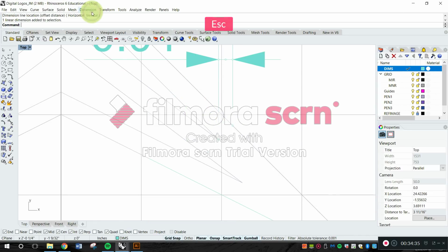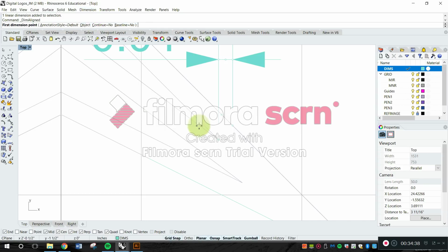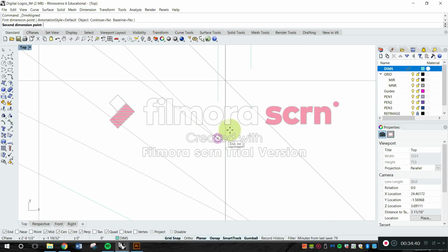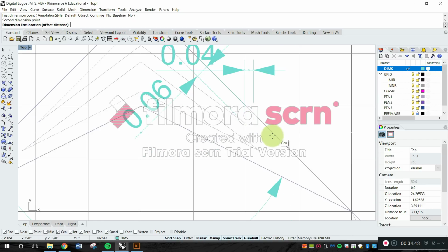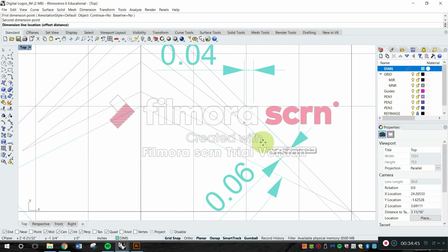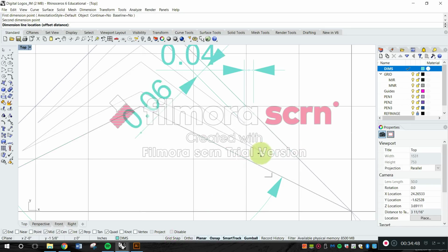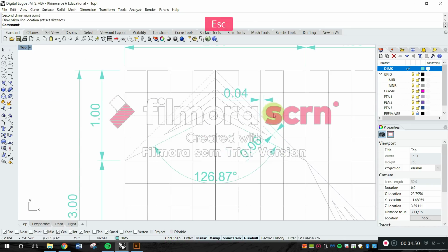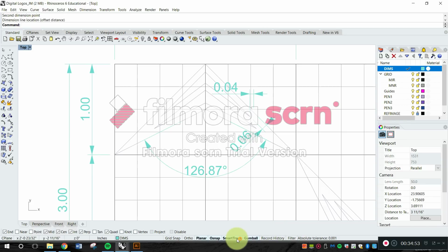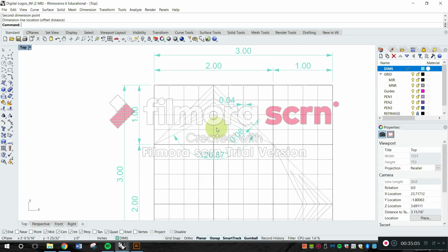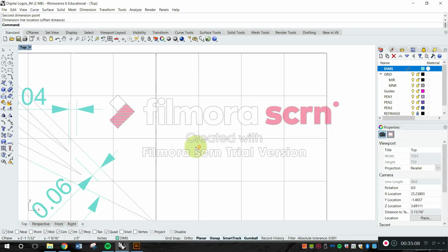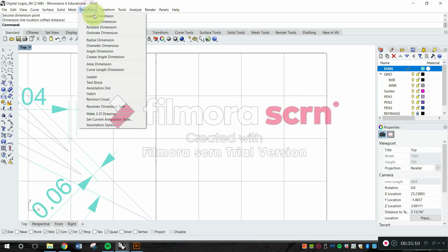Because the right dimension should be an aligned dimension, which I'll show you right here. It's different. We go again to the perpendicular right there, and it's actually that. I'm going to turn off grid snap so that I have freedom to where to drop it right now. But can we see that difference? So the linear dimension gives you just that, a linear dimension, whereas the aligned gives you an angular one, and I think maybe even here it's a better way to show it. Dimension, linear one.